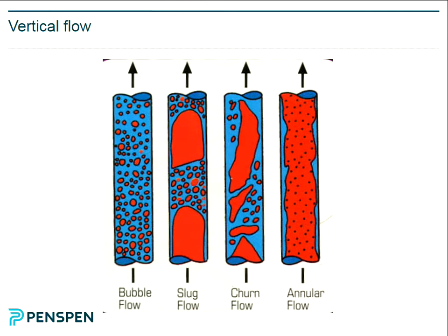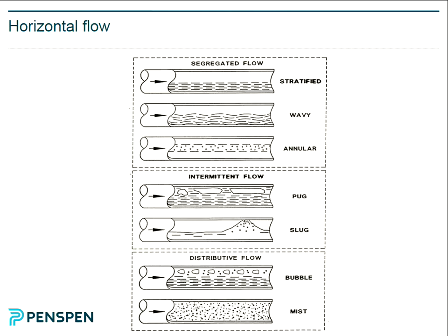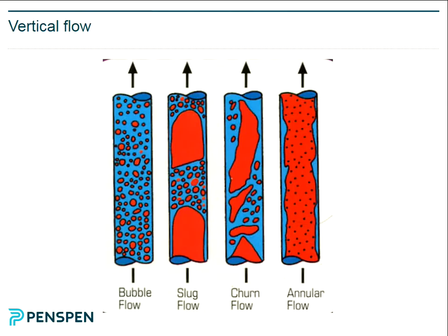The gas reduces the well-specific gravity, decreases the static head, allows the flow rate. If you keep increasing that gas, though, you'll find eventually, because the velocity in here is increasing, it will choke. So there's an optimum value. If you start increasing that gas, the flow rate will improve, and then it will start to get worse.